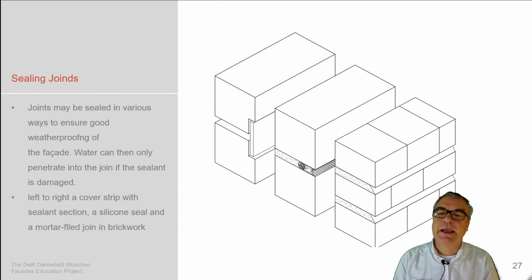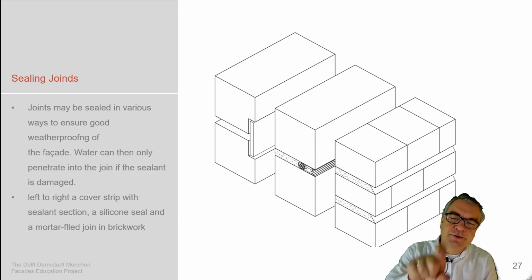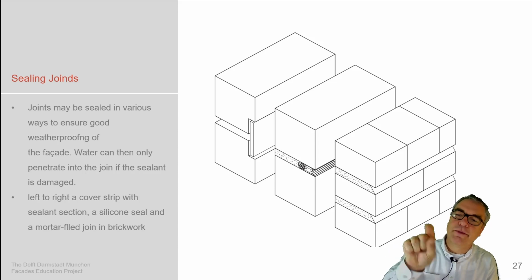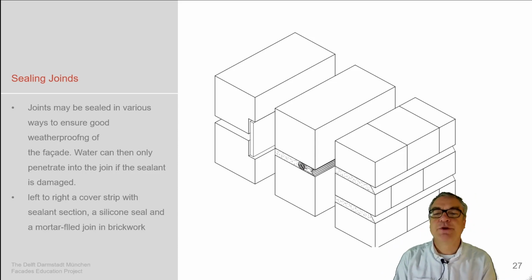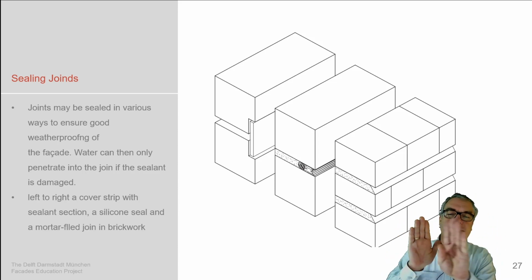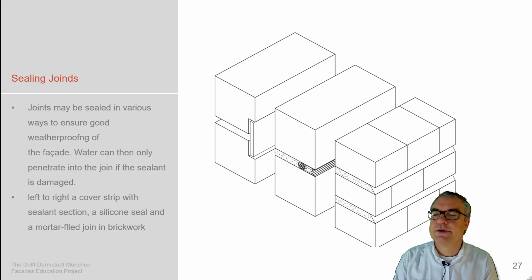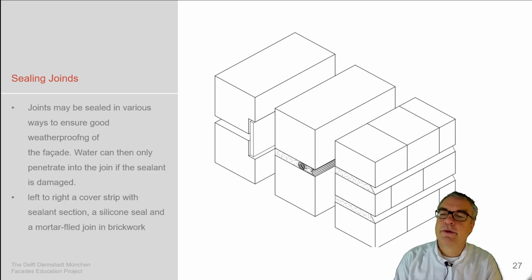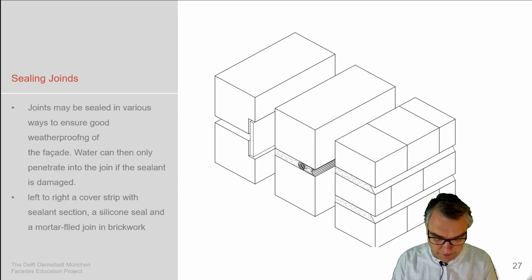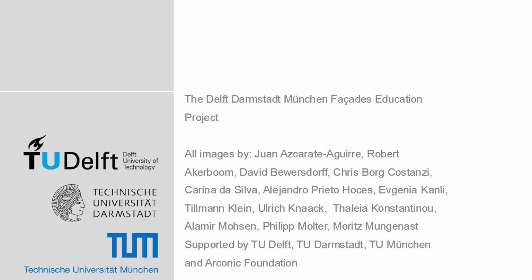which brings us to sealant opportunities. It's at the right with a strip, which is more an aesthetical part, or the middle one with a silicon line, which allows these changes of dimension, which allows these compressive situations, or far right, the more common way of doing it with a mortar-filled sealant for enclosing the joints of these brick systems.